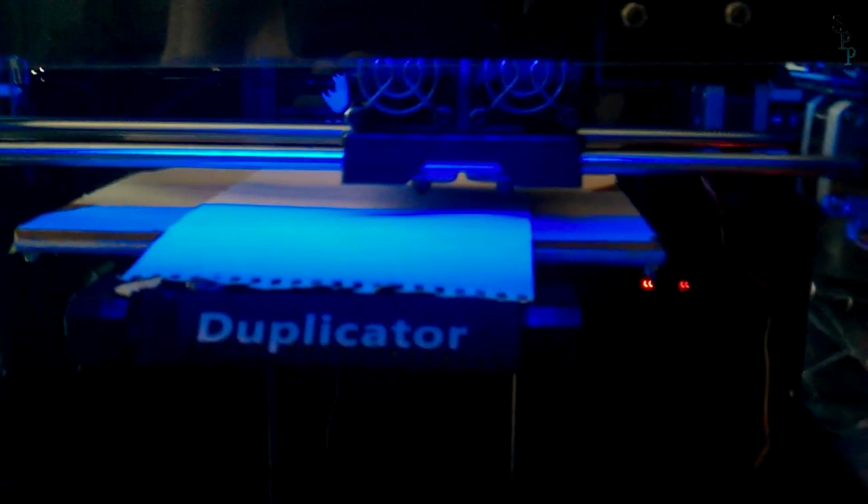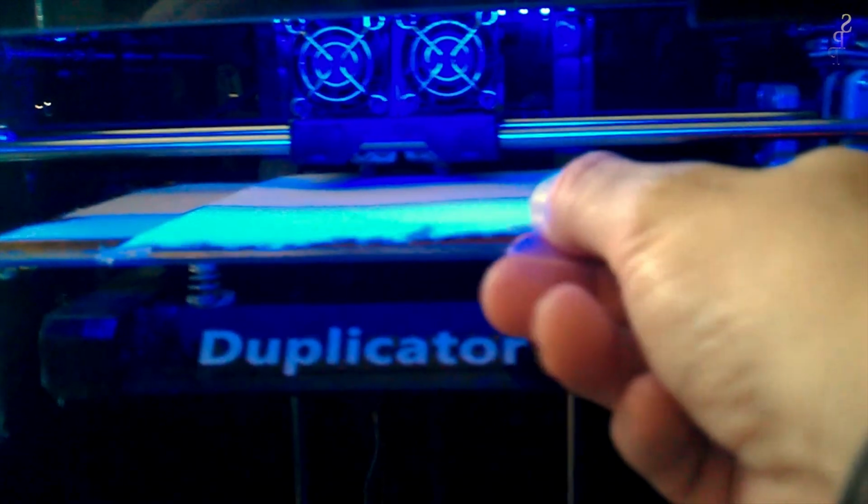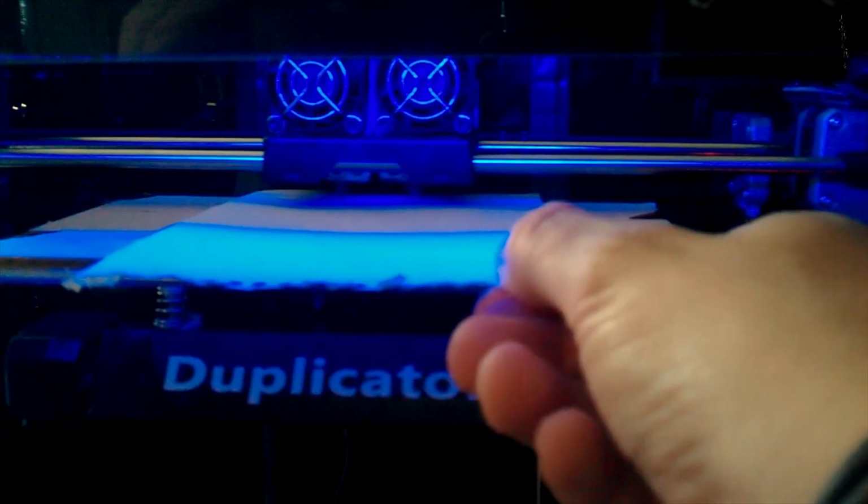With this piece of paper, this is really just to set the height of the hot end or extruder to about 0.1 of a millimeter above the surface. And you get some instructions on the menu, and then the printer moves to several locations. Exactly how it works depends on the version of software you've got in the printer. I've got the factory build software at the moment. If you have some later versions like Sailfish, you move the head around yourself.